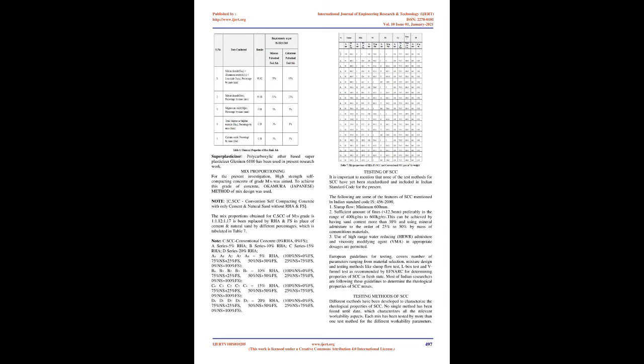Hence the amount of silt content in the present filtered sand is investigated by using the hydrometer test and results are shown in Table 4. Coarse aggregates: crushed granite jelly of size 12.5 mm down conforming to IS 383-1987 was used, as shown in Table 5. Rice husk ash: the rice husk ash was obtained from Maddur, Mandya district. RHA used for investigation was tested in the civil lab and the chemical characteristics are given in Table 6.